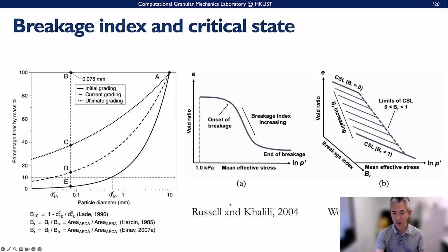critical state, in a crushable granular sand or granular material. We can define a certain breakage index, like Hardin's, where we define the area surrounded by the crushed fine particles compared with the original one, and then we define the so-called breakage.